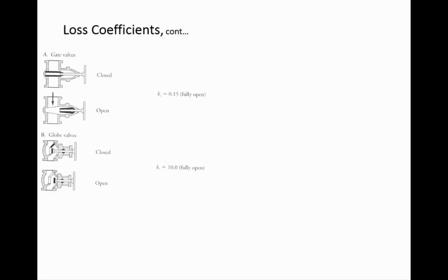If you make the pipes big, then the system costs more money. But if you make the pipes really small, then people don't have very much pressure at their house. And so, like, there's this range of acceptable values that you're trying to balance, where you want to make the system as cheap as possible but also deliver required pressure to different houses. And so when you are thinking about how much pressure do I need to deliver to someone's house, you have to think about what sorts of valves are used in a home.